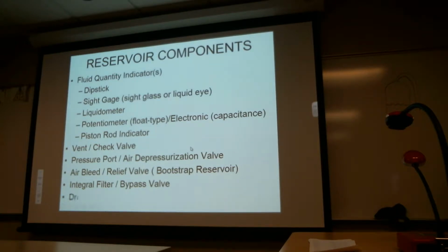Okay. And we might find a drain. Not all reservoirs have them, but many of them do. It provides the opportunity for removal of all of the hydraulic fluid, maybe for rinsing the sediment out of the bottom of it if there's been a buildup of sediment.